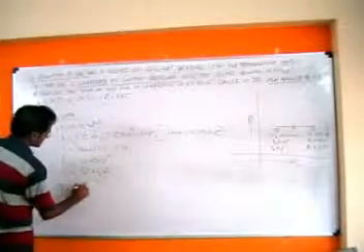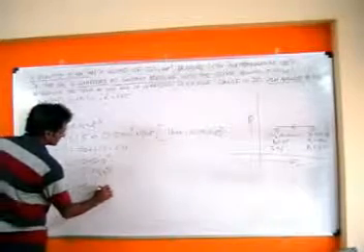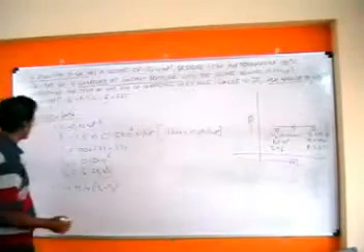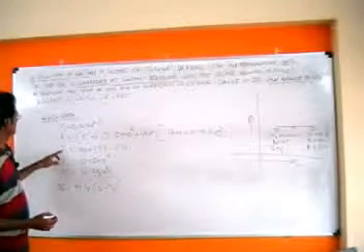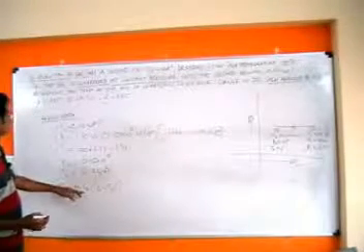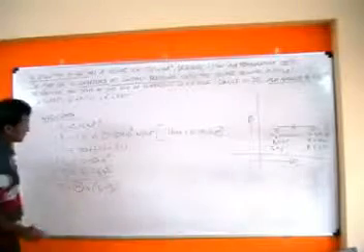We go to the next question of finding out the change in internal energy. We have the standard formula of mCv into T2 minus T1. Since we have the values of temperatures at the start and at the end of the compression, and also we have the value of Cv, we need to find out the value of m.